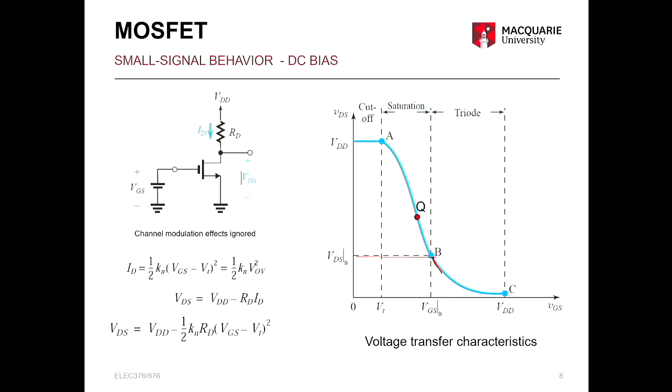Yeah, so in the amplification, some part of the signal, when it goes to one extreme, gets clipped off. So it's not a pure sine wave anymore. So in the FFT, you will see more frequency components. In the real world, that will manifest as noise or distortions.